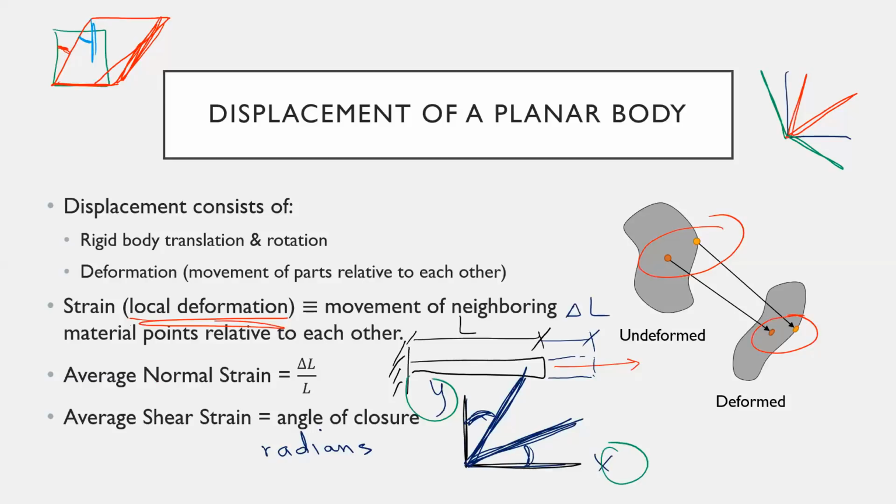And so it's specifically when you have your X and your Y, those angles closing is our positive shear. And so conversely, this corner here, the one that starts here, it has a X and negative Y as its starting directions. And so therefore, because those are opposite signs, it's the reverse, that a positive shear opens that angle.